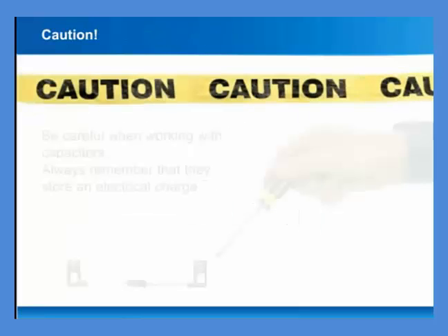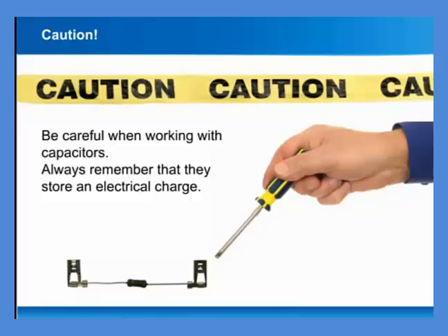Be careful when working with capacitors. Always remember that they store an electrical charge. The use of a 2-watt, 20,000 ohm resistor to discharge the capacitor is recommended. Placing the blade of a screwdriver with an insulated handle across the capacitor leads will also discharge the capacitor, but it can damage the capacitor.